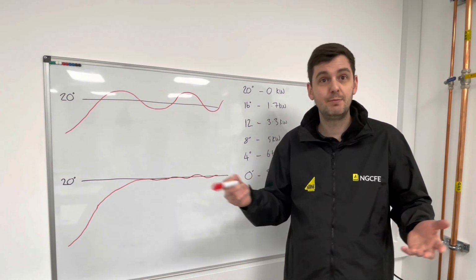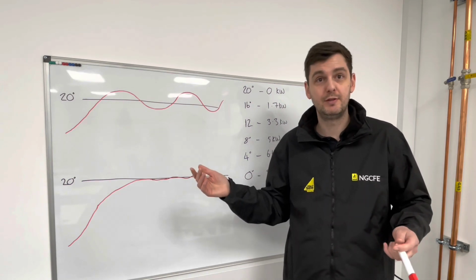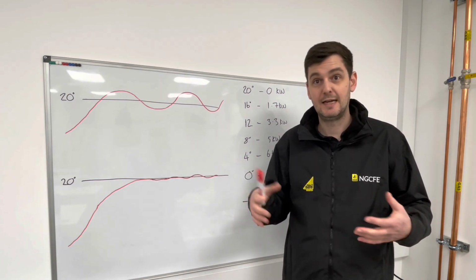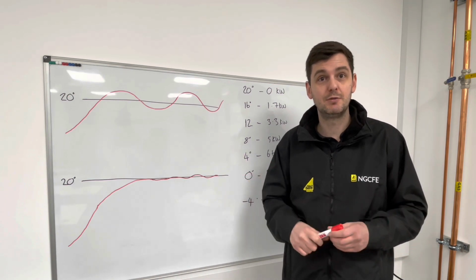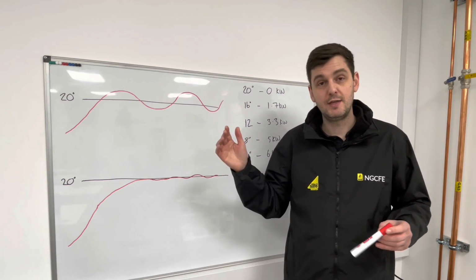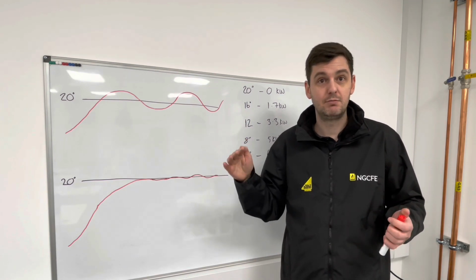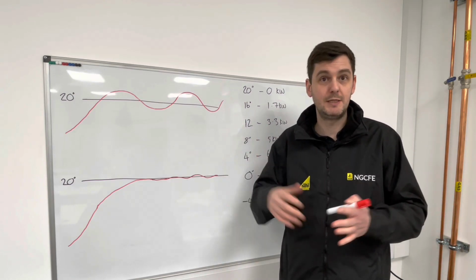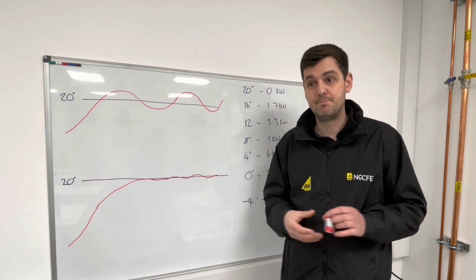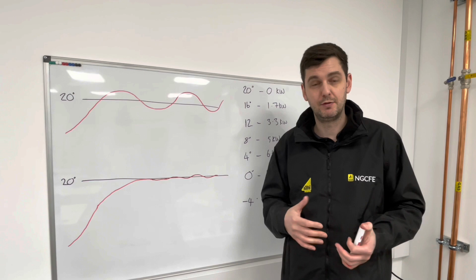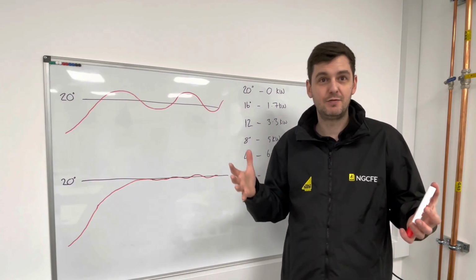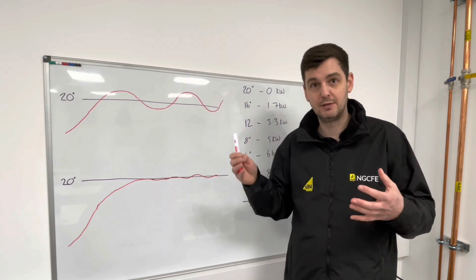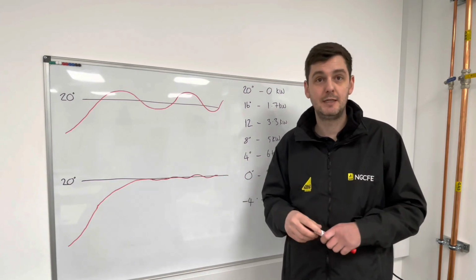Someone who's retired, for example, might want to spend more time at home through the day, and therefore weather comp will be perfect for them. If they've got an air source unit, or if their heat generator is a condensing boiler or something that's, what we see, more energy efficient, you would use the weather comp settings with a setback, so that the boiler doesn't have to work harder in the morning to get the room and the property back to a desirable temperature. And also the mass of the property, so the brickwork, the floors, will also act as radiators, for lack of a better word, and they will store some of the heat and maintain it, so that the heat source doesn't have to work harder to get the property to temperature.